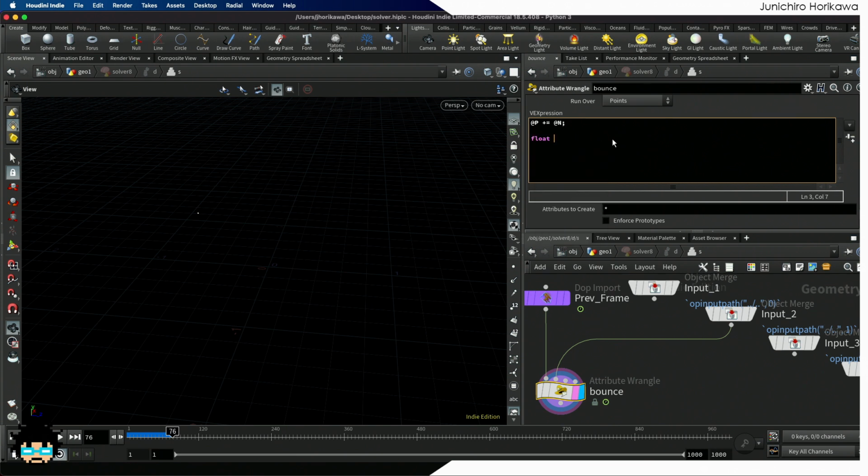First of all, I'm going to create output parameters in order to use xyzdist. One is the primitive number and one is the UV value. And retrieve the closest distance between the point and the surface using xyzdist from the second input, from the current point position, and prim and UV will be fed as output parameters. Now by using these values, you'll be able to get the projected point position as well as the projected point normal direction.